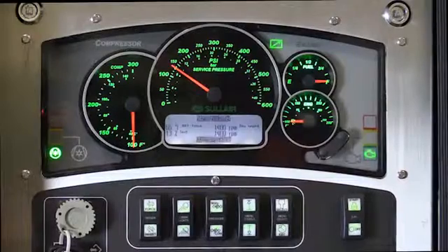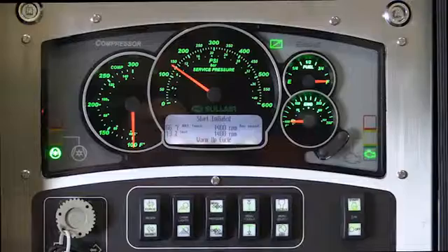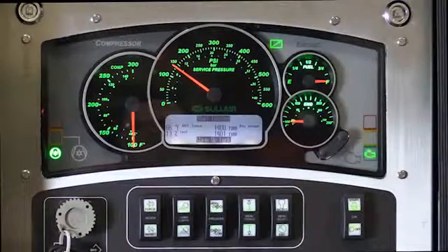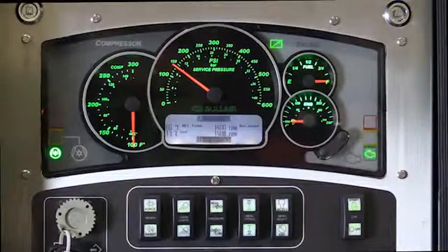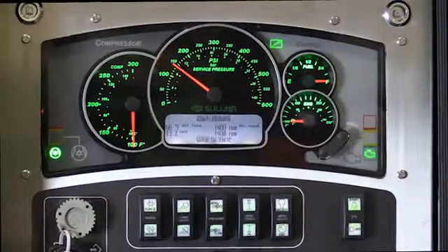During the warm-up, the C-Pro controller is energizing the start-run solenoid. This diverts the reducing regulator signal through the start-run solenoid valve directly to the control circuit, i.e. the closing feed port of the inlet. This holds the inlet closed so no more air can enter the compressor. This is what keeps your pressures down.